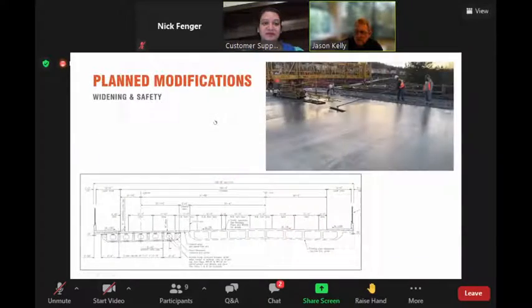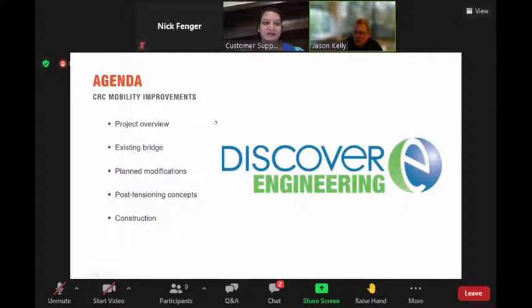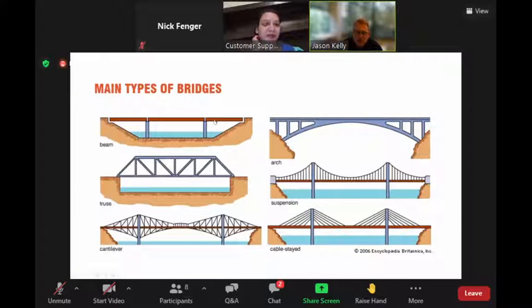A beam bridge is, well, I would say a beam bridge is typically the cheapest and easiest, cost effective, but arch bridges are a pretty economical shape. They're a historical shape. I mean, the Romans and probably even before them figured out how to build arches. The thing with arches, though, you have to have really strong ground. Where the arch lands, this needs to be bedrock. So we don't have a lot of arches here in Oregon because usually our bridges sit on dirt, but probably beams are the easiest. They're the most basic. Arch bridges are pretty functional if you got the right support for them.